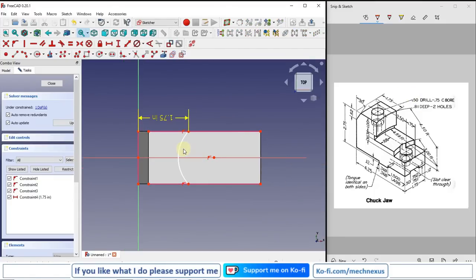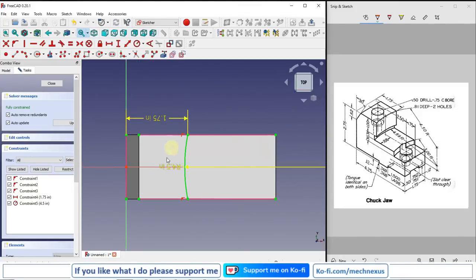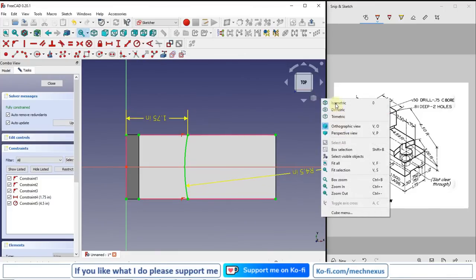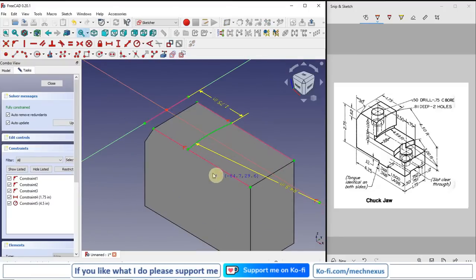Now our arc is still not constrained because we have not given it a dimension. So this arc dimension here is 4.5 inch. So I will give here radius and I will say it 4.5. And I will switch to the isometric. Now we will close our profile.